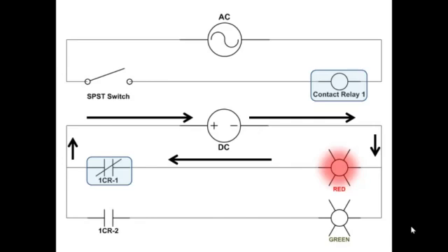Now remember that airspace in the previous diagram between the AC circuit and the DC circuit. You can really see the airspace here, but you can no longer see that these two relay contacts belong to that relay coil up there. Therefore we have to put nomenclature on them.